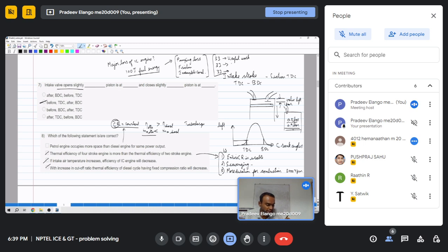So the second major portion is heat transfer. For an air-cooled engine, the heat is transferred to the air, and for a water-cooled engine or liquid-cooled engine, it transfers to the coolant liquid. So this is like one third of the fuel energy goes into cooling the engine. And what is the remaining 33%?